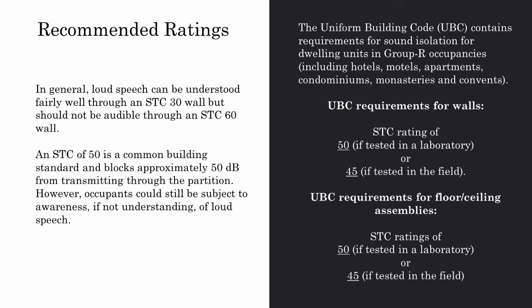UBC requirements for floor or ceiling assemblies. STC ratings of 50 if tested in a laboratory or 45 if tested in the field. The field test evaluates the dwelling's actual constructions and includes all sound paths.